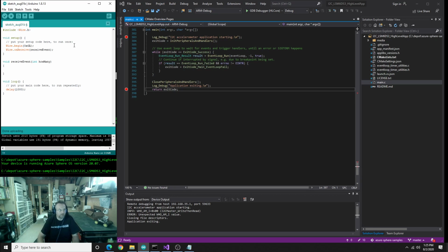And I think what would be useful at this point so that we can see what's happening would be to actually use the Serial library so that we can use the serial monitor that's in this thing. So let's go ahead and do a Serial.begin. And you can pick whatever speed you want. Most of the samples use 9600. It's kind of slow, so I typically go a little bit faster for the speed for the serial port.